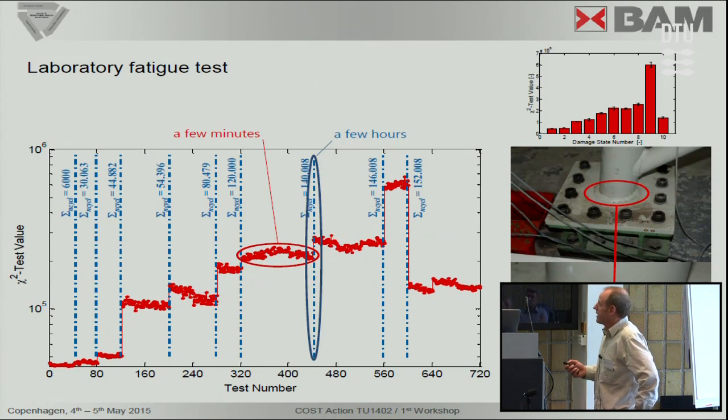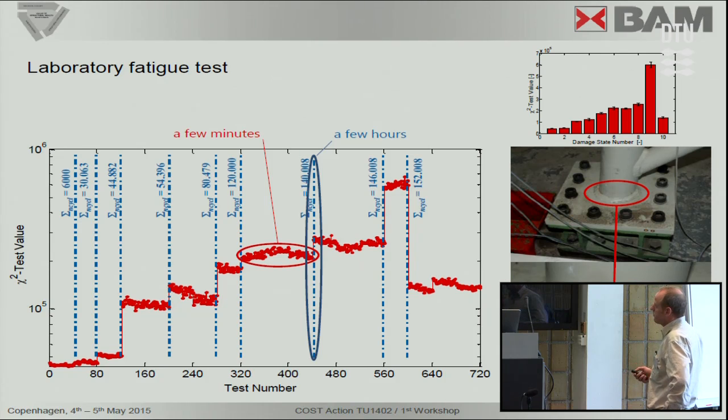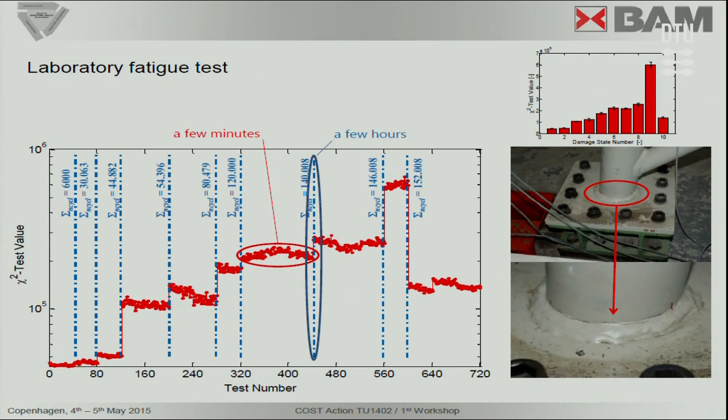This is the result of the fatigue test. In this diagram, the red dots are the vibration test, the SSDD test, the indicator of the damage, and the blue lines are the load cycles, which took a few hours. You see here a steady increase of the indicator of the feature,